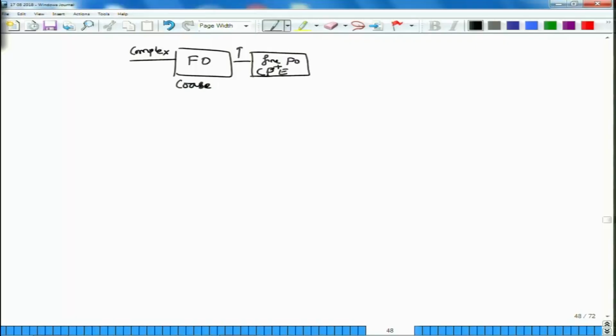In digital methods you are going to look at the samples that you have gotten here. So this is the sample that you have obtained, and using these samples you are going to estimate the phase. This sample will be a function of the actual symbol that has been transmitted. That symbol itself could be a complex symbol indicating the higher order modulation that we have talked about. It will also be a function of the phase, and in this phase there are two distinct phase components that we want to talk about.